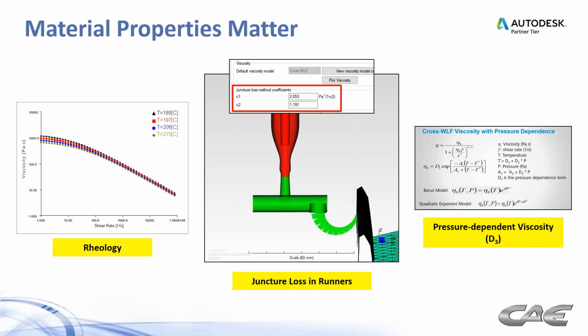That is how the material is shearing, which is related to the fill speed, of course, and to the wall thickness, how the viscosity changes as a function of shear rate, and also how it changes as a function of temperature. You see the different temperature curves there. So viscosity is a product of shear rate and temperature at its basic level, and these are the curves that govern the flow behavior of the material as it passes through the runner system, the gate, and the part.